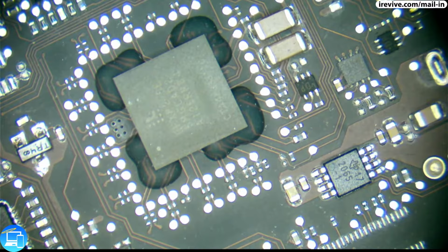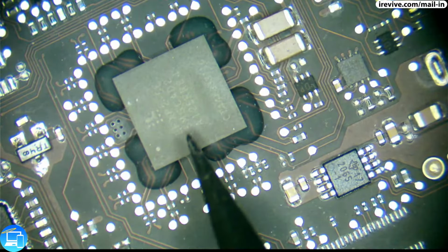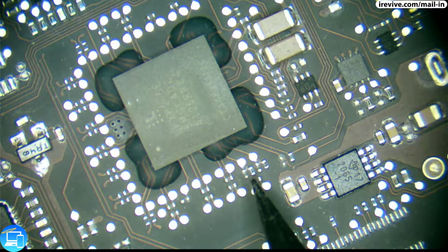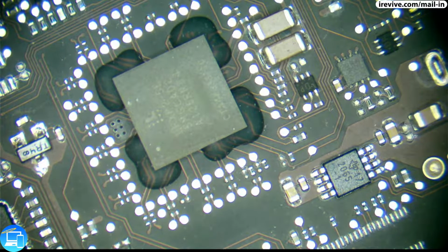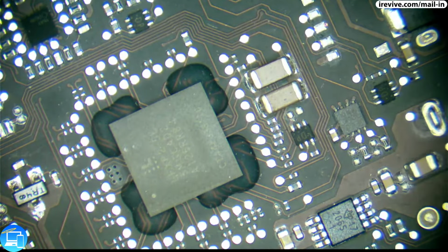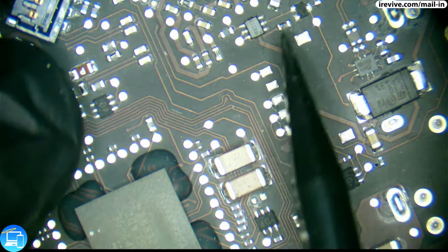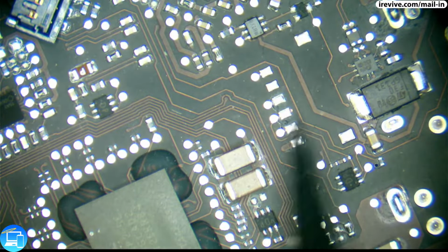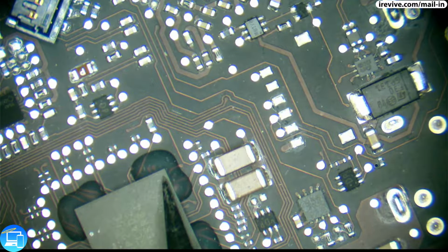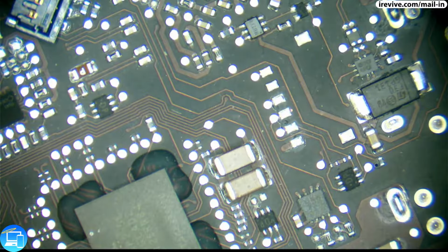Okay, so this is our Gmux chip. This is what's responsible for sending power between the integrated graphics or the dedicated AMD graphics card. It's also responsible for switching between the two graphics cards. But if you look here, there is an unpopulated terminal where Apple themselves would actually program this Gmux chip. And so DasDude, Colin, and I'm so sorry I forget his colleague's name, have reverse engineered the firmware on the Gmux to be able to bypass the AMD graphics card. Just through firmware, essentially, we are going to be disabling the dedicated graphics card.